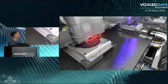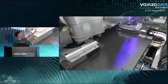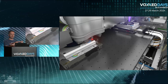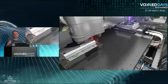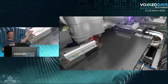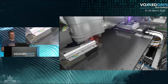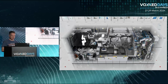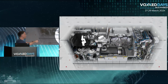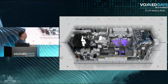Now when you look at the entire machine, so at the right, it's currently being printed, the pattern. On the left, they adjust the wafer to the correct position. So before we print on it, we first make sure that the wafer is positioned correctly. And we do that in parallel, basically, to be able to process more wafers in the same time. But even while it's being printed, it's also still adjusted how the wafer is laying on that wafer stage. And then in total, it looks like this. So at the top, you see the different reticles being changed. And at the bottom, you see wafers coming in, being measured, and then being switched to the part where they're printed on.